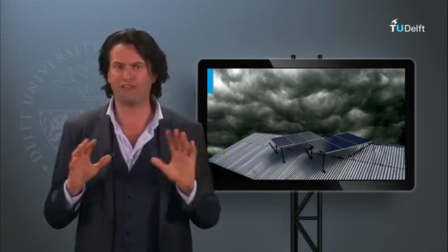Now, you might be thinking, what happens if it's not a sunny day? Or even worse, there's a string of dark days, like in many parts of the world. In such a case, if you have to meet the load demand, then there is no option but to oversize the battery so that the expected days of autonomy can be dealt with.